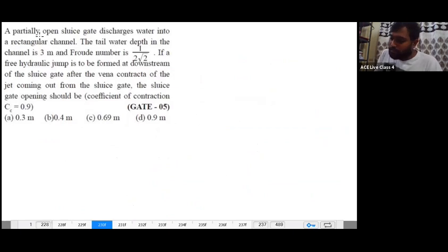Yes, you see a partially open sluice gate discharges water into a rectangular channel. Now the tailwater depth in the channel is given as 3 meters. The tailwater depth means y2. And the Froude number is 1 by 2 root 2. If a free hydraulic jump is to be formed downstream of the sluice gate after the vena contracta of the jet coming out from the sluice gate, the sluice gate opening should be...